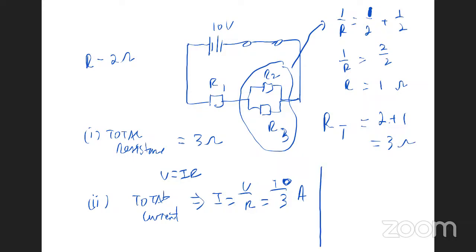I asked one little question, right? What will happen to the current when it reaches here? When the 10 over 3 amperes reaches that junction, what will happen to it? It was split up, right? Very good. And if the resistances are equal, how will it split up? Equally. So if the resistances R2 and R3 are equal, that 10 over 3 amperes will split up equally. 10 over 6, 10 over 6. All right? So sometimes it really is a place to work out.